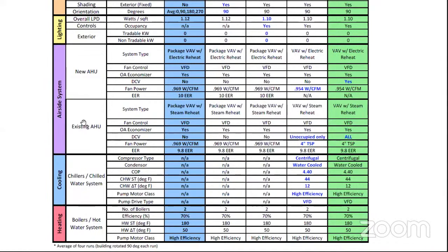Yes. So what happens is you can keep one sensor in the space, and the sensor will check the CO2 value, measured in ppm, parts per million. One CO2 sensor inside the space and one outside the space, whenever the differential crosses 530 ppm, immediately the fresh air damper will open.